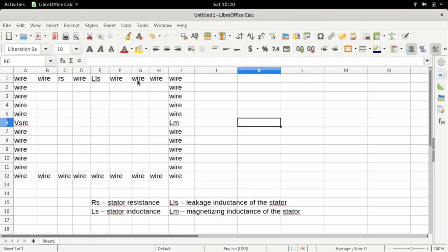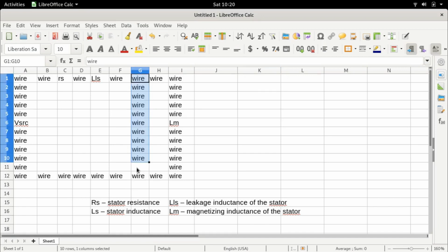The reason why I'm doing this is because it's important to understand that when we have a magnetic field, this magnetic field results in certain losses which are very specific to magnetism. For example, we have eddy current losses. We have hysteresis losses. These losses will result whenever we have a magnetic field, right? So these losses are represented by a core loss component, right? Just could put this, and here I'm going to denote it by RC.